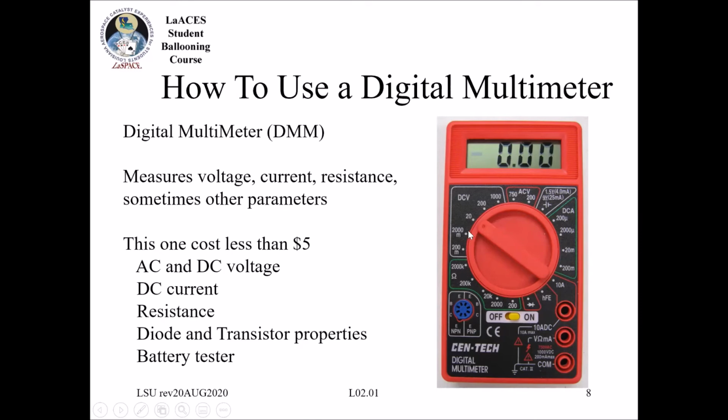So again, whenever you're looking at these different things that you're going to be measuring, try to set this range here so that you can get the proper reading. That's how this particular one works, but it may not be the way that a different meter works. Also important over here is where the leads go. Hopefully with the meter that you're looking at, there are 2 leads, a black lead and a red lead. The different configurations we're about to go over, but I want to make sure that you understand that those will be plugged into one of these configurations here.